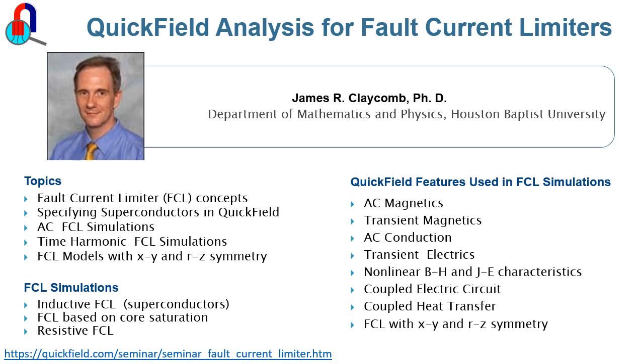So the simulations that we're going to be doing today: we have the inductive fault current limiter simulations using superconductors. And also there's a fault current limiter based on core saturation and desaturation that doesn't necessarily involve superconductors, as well as resistive fault current limiter simulations. So those are the three types of fault current limiters we can simulate.